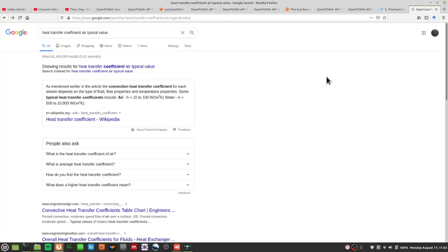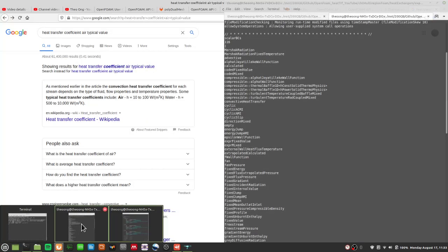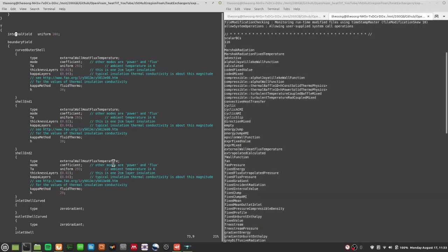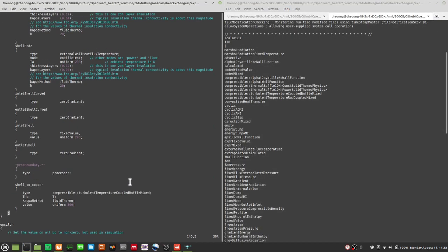So this is one interesting boundary condition you can use to explore heat loss to the environment. You can actually simulate that with an appropriate heat transfer coefficient and a plausible estimate for an insulation layer around your shell. So you can simulate a little bit of that.